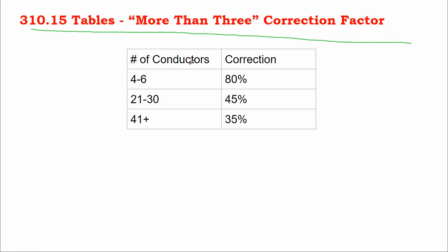The reason why some of these tables are incomplete is I can't give you a complete copy of the National Electric Code for you just to print out and have as a handout, unfortunately. So there's middle data inside of here, but what we're trying to do is illustrate the point. The more conductors you have bundled together, the greater the derate.